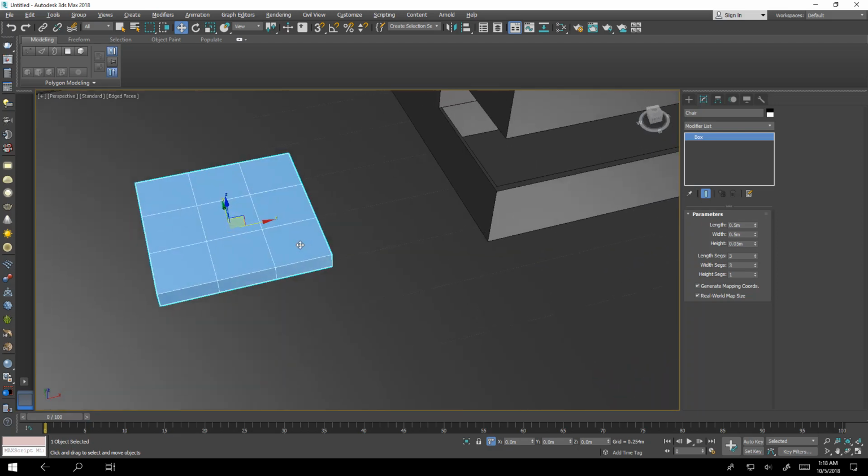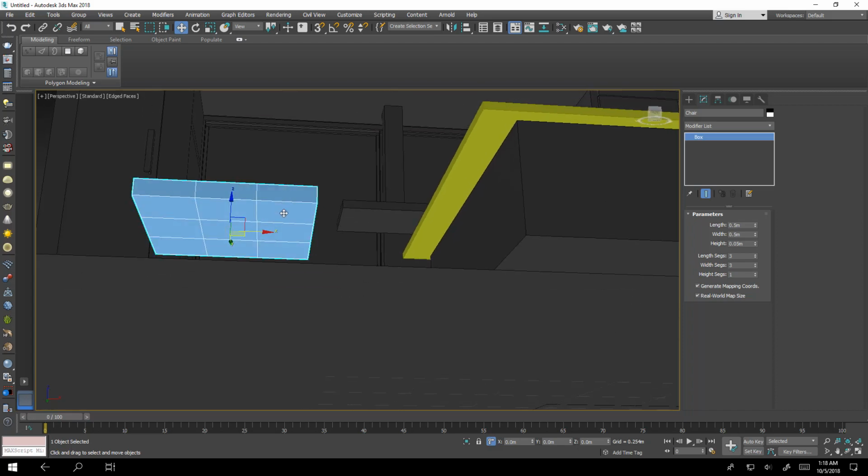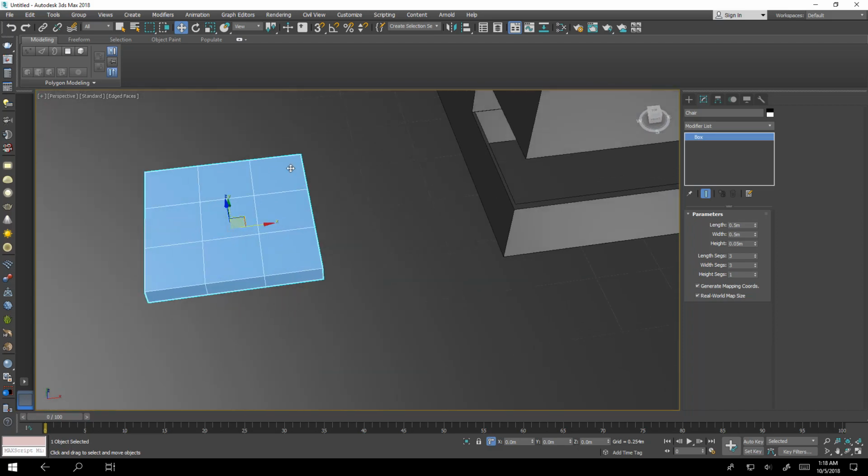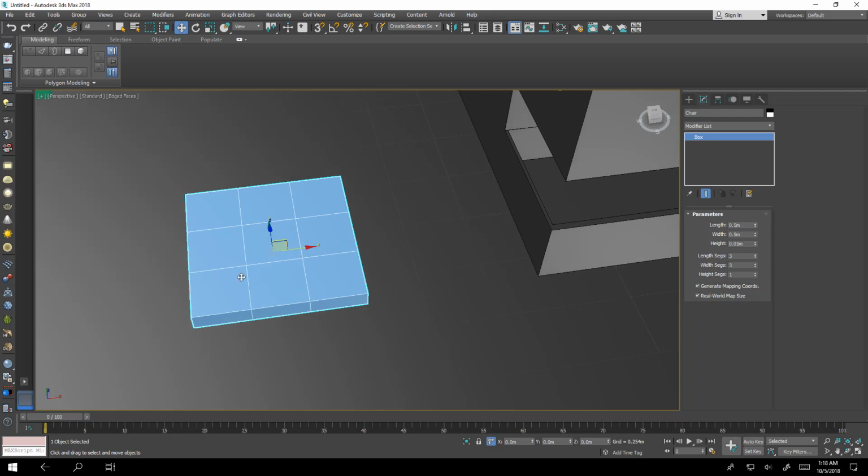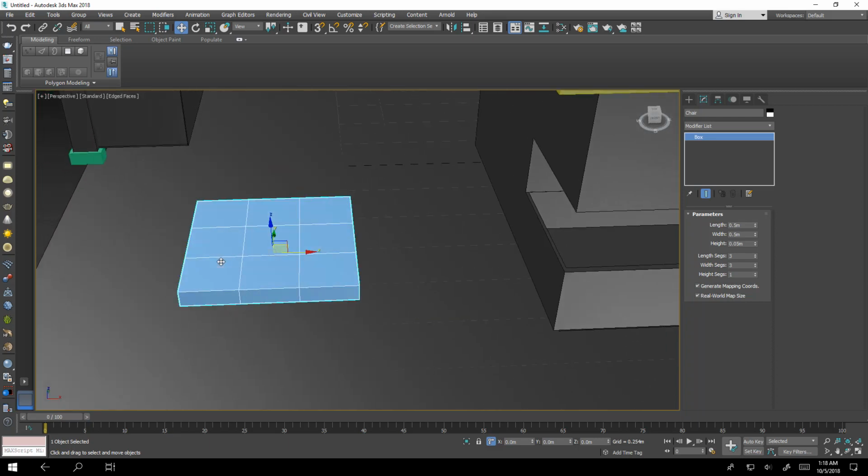I want first to make the 4 legs. So I will calculate or design or plan my segments. It's better to plan first, but beware, it's better to put little vertices or segments than to put more. Because after converting this to editable poly, you can add or remove segments as you like, but adding segments or vertices is easier than subtracting. So keep in mind this rule.